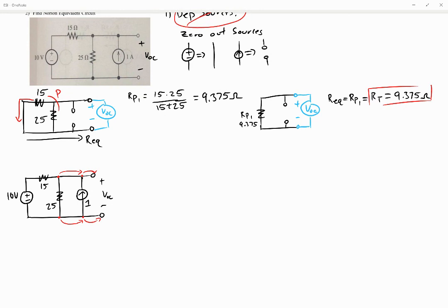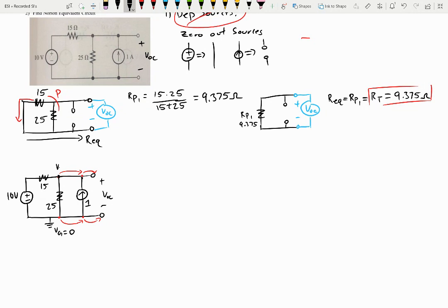And since we have two separate sources, this is kind of pointing us in the direction of doing a nodal analysis. So I'll just go and write that out. But to do that, we'll need to drop a ground. V of ground is equal to 0. And then let's name this point V of A, just for convention wise, we'll name it V of A. You have to do this during the test for nodal analysis, just name your points.